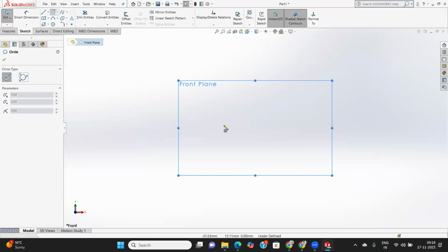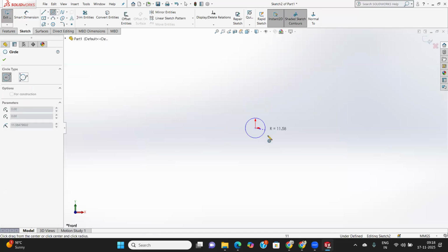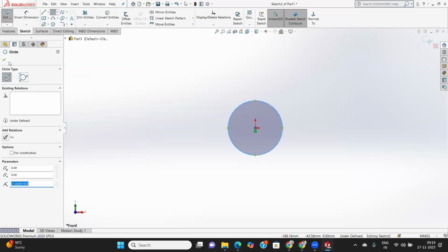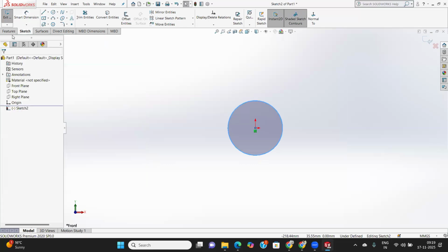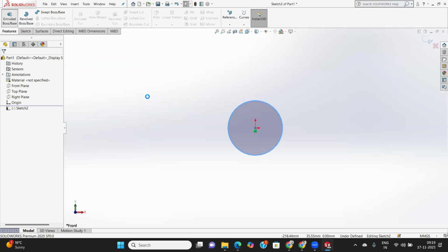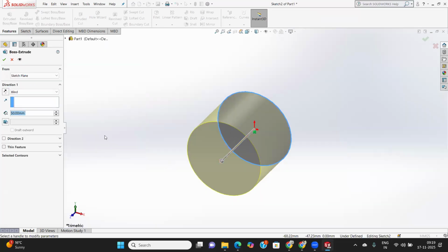If you select here to make the circular way, I also make a circle right there. If you extrude it, then what happens? Here we got this part also. One thing you can see is that you have the options of this also. Here we have multiple options. First of all is blind. And then up to vertex, which means this vertex will be shown another way.